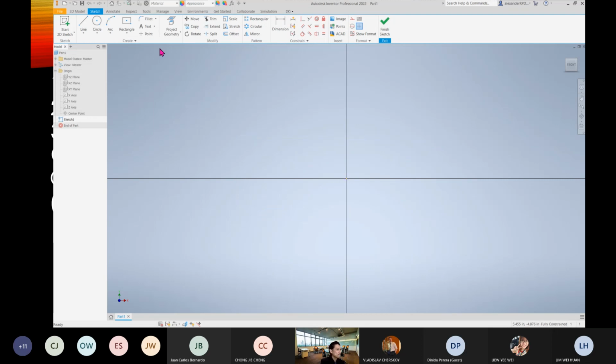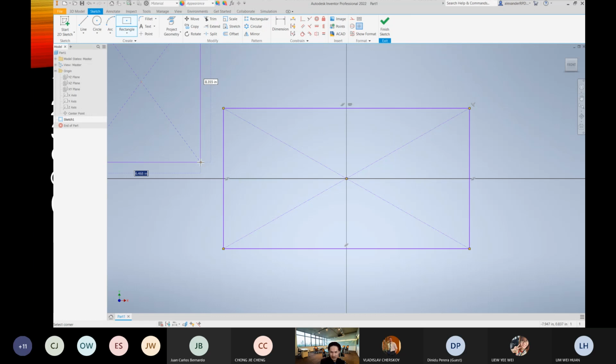Okay, one more time. So I select the rectangle, the third one, and then I click, and then I expand it. I don't care about dimension, I just drop it. And then my rectangle instruction is still active. To deactivate it, press the escape button, or else later when you click whatever, you will still continue to create a rectangle. So I escape to end the command.